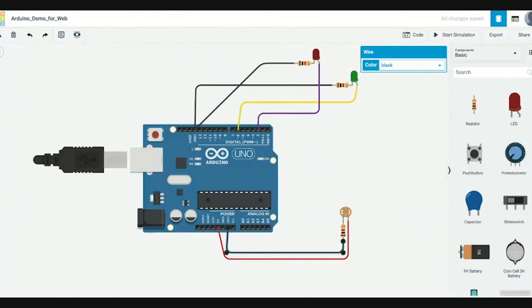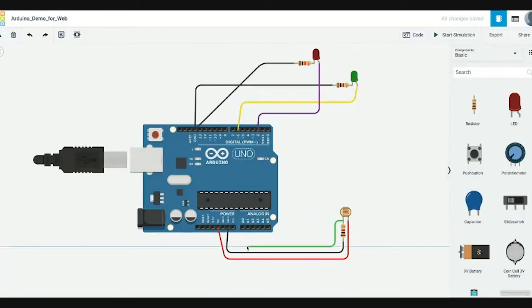But what we've just done is the equivalent of plugging a light into a wall socket. We're supplying power to something that is not returning to indicate its state. Is the light on? For instance, if we use our eyes, we can tell a light has been plugged in because the room is bright, but this photocell actually needs to have a third wire connected from where the pull-down resistor connects the photocell to the ground pin on the microcontroller. And this is so that we can actually tap the electricity and read it on a pin.